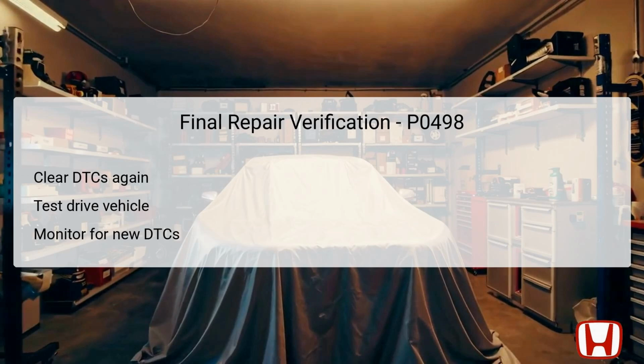Upon completing all necessary repairs, you should conduct a final verification to ensure the problem has been resolved. Begin by clearing the Diagnostic Trouble Codes, DTC, using the HDS again. This reset allows the monitoring systems to refresh and begin a new operation cycle, free from past errors. After clearing the DTCs, it's essential to perform a test drive of the vehicle under various conditions.